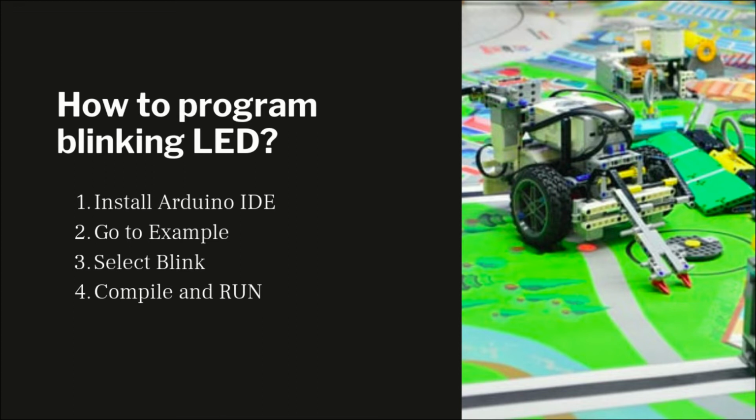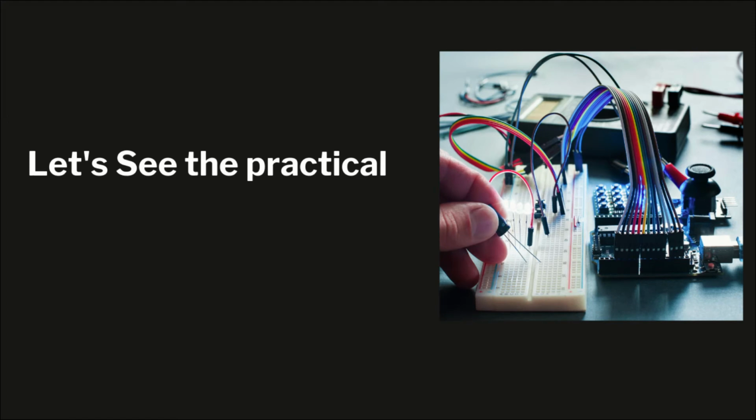For that you need to do these 4 steps. Number 1, install Arduino IDE. Number 2, go to the examples. Number 3, select blink. Number 4, compile and upload. Let's see the practical and understand how all these things work.